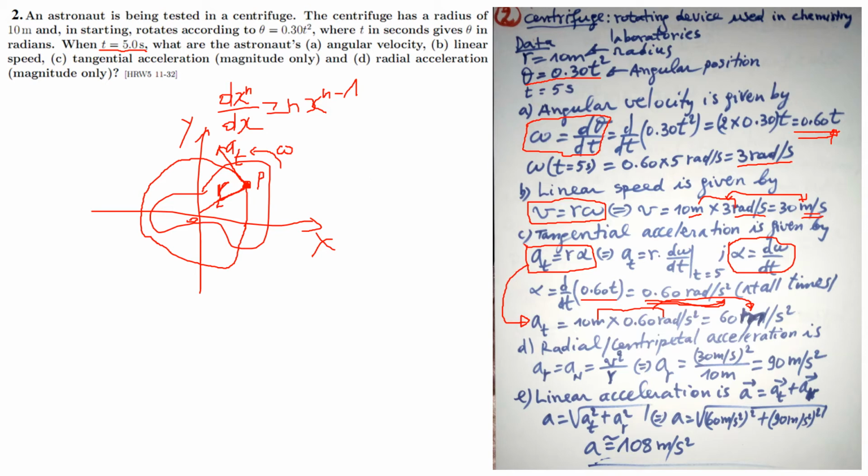This component is called radial acceleration because it is oriented towards the radius, or also called the normal acceleration a with index n. Normal acceleration means centripetal acceleration. The centripetal acceleration is an acceleration which allows the body to maintain a circular trajectory.